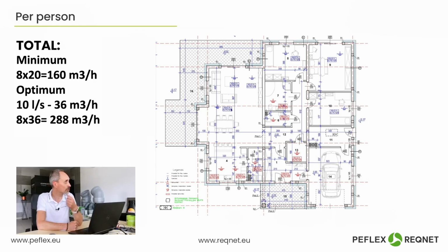So again, referring to paragraph 4 of this regulation, rooms intended for human occupancy are divided into rooms for permanent stay and rooms for temporary stay. Rooms for permanent stay are those where people can stay for more than 4 hours a day, so a bedroom is definitely such a room, but a living room can also be considered as one. I don't know, perhaps a dedicated dining room complete with a small kitchenette, or indeed any suitable place where individuals who are intended for a permanent stay within the building's design can comfortably spend more than just those 4 hours during the course of the day.